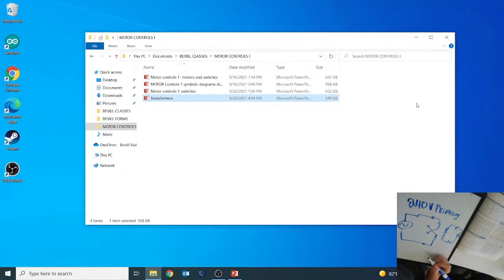All right, so if we're wanting to convert 240 volts to 120 volts, what did I tell y'all it needed to be in? Parallel. Ha! Dylan was listening. So how would we connect this in parallel? Hang on. Let me just go ahead and draw this out. So we got 1, 2, 3, and 4. How would you connect that in parallel? You need a little jumper, wouldn't you? Dylan, what number would I connect to what?